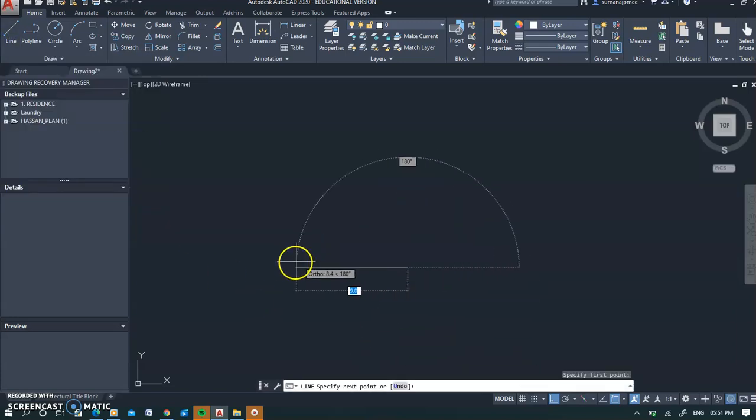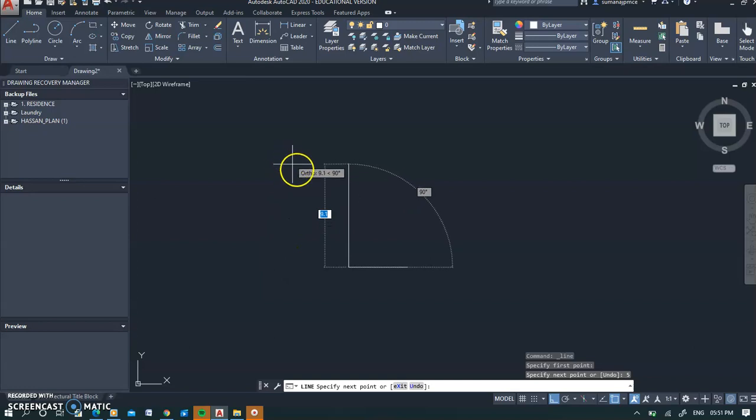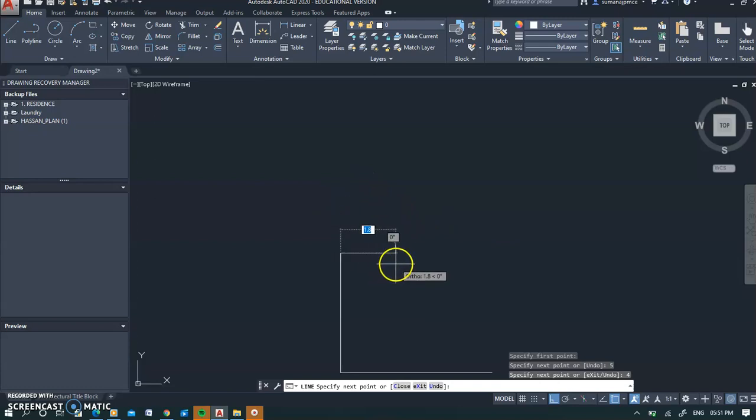I start from a point and then I'm going right to about 5 meters, and then I'm going up vertical 4 meters. Okay, let's assume that is a room, and then I will get a wall. So I will keep that wall thickness as 0.3. I have not disconnected from the command. I'm continuing. Okay, so next I will take another line of 2 meters,